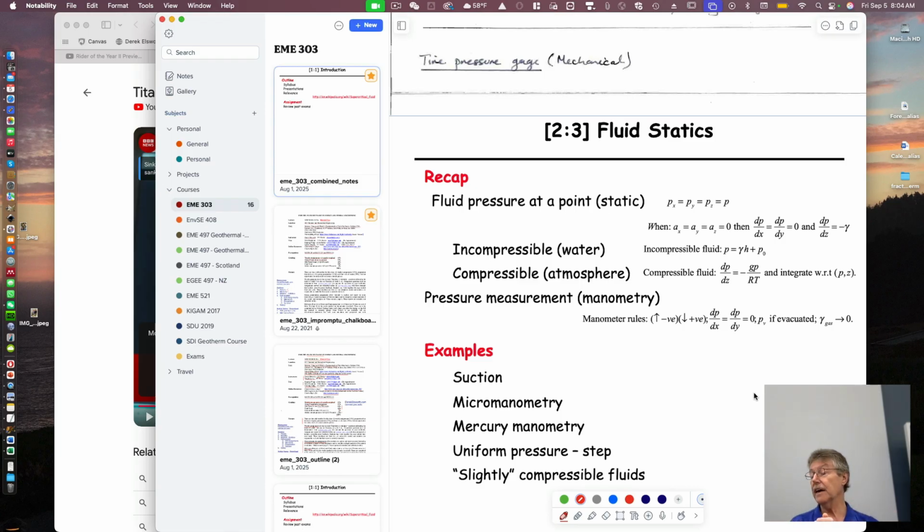You can get speed from GPS also, but that's not going to be airspeed, because if you fly east to Europe, you know it takes less time because you're with the jet stream, maybe 100 miles an hour. And if you're coming back, it takes longer because you're flying against the jet stream. And of course, planes fly and the aerodynamics conform to airspeed, not ground speed.